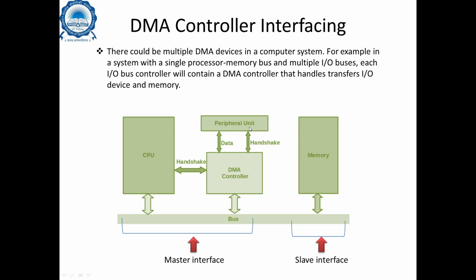The data transfer also happens from the peripheral unit, which is the A to D unit, and it will send the data to the DMA controller, or the DMA controller will read it from the ADC data register and put it in the DMA FIFO buffer. And this is the RAM where ultimately the data from the FIFO buffer will be put through the common bus in the respective destination address of the RAM, and it will get stored here.